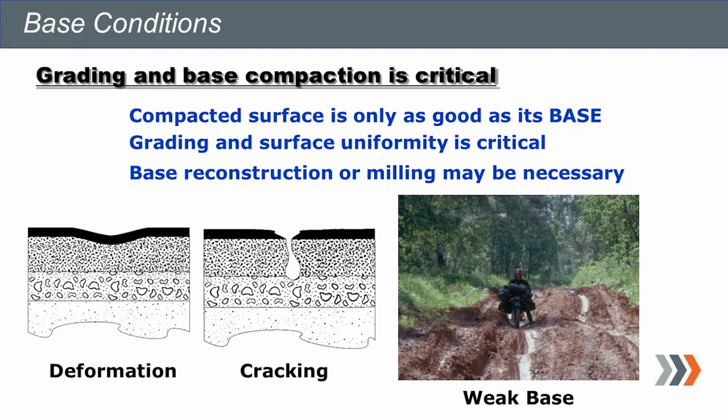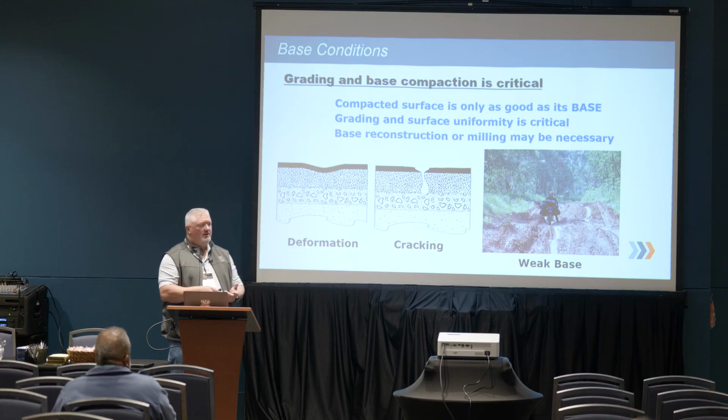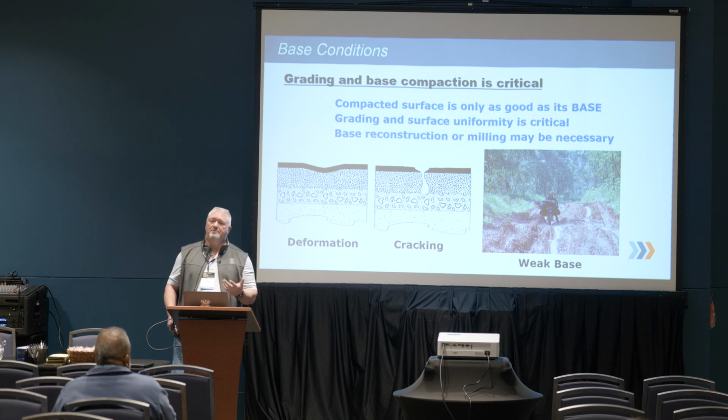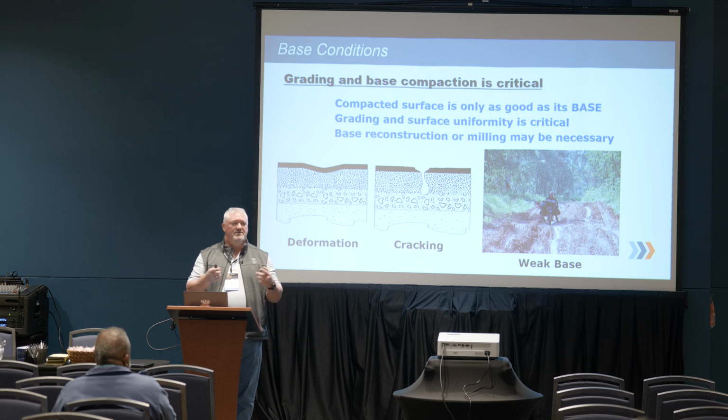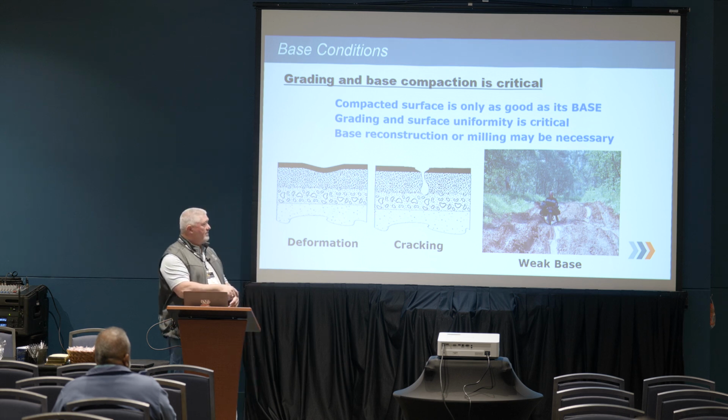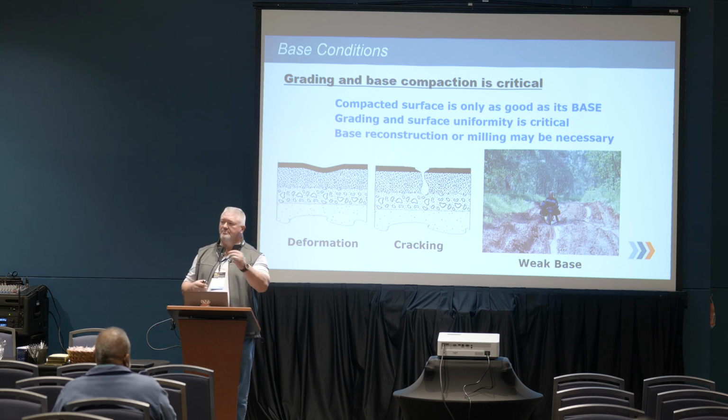The other thing is, what are we paving over top of? What are my conditions? Do I have something like this that I can just get away with maybe mill and fill it? Or if it gets down into the base, I don't want to just mill and fill it because then it's like putting a Band-Aid on something that needs stitches. It's going to come back up. We definitely don't want to pave over something like this because remember, the paver pushes the truck, don't pull the paver, with what we're trying to do.